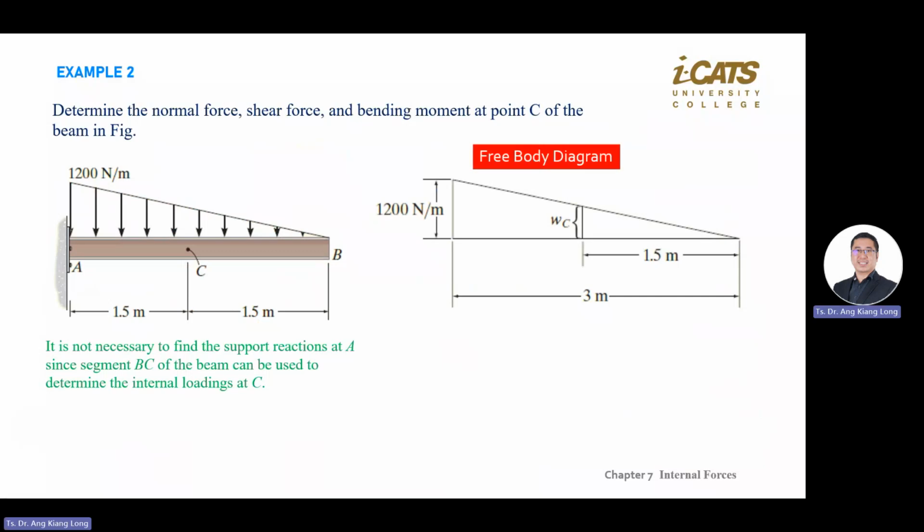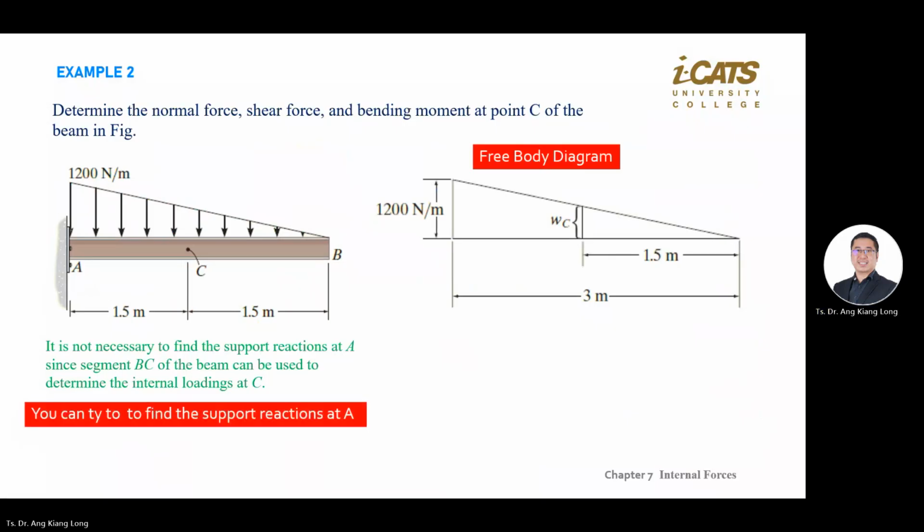So here I just highlight that it's actually not necessary to find the loading at A in this case, but it's always highly recommended that you find what A and B are. Because with distributed load, there's an easier way to find the internal loading. Again, in a normal test or final exam, always go and find the support load. In this case, if you find it, also can.